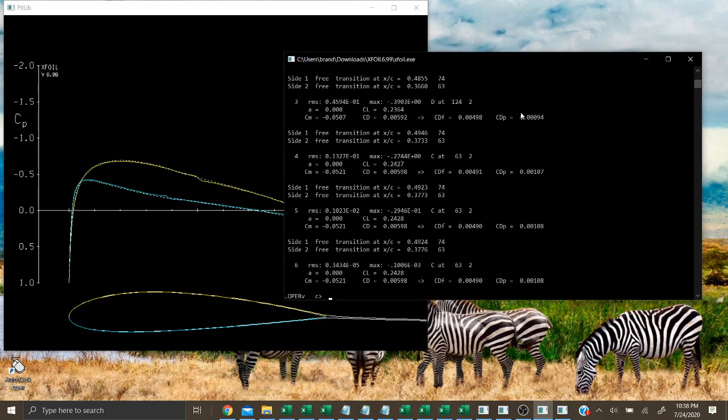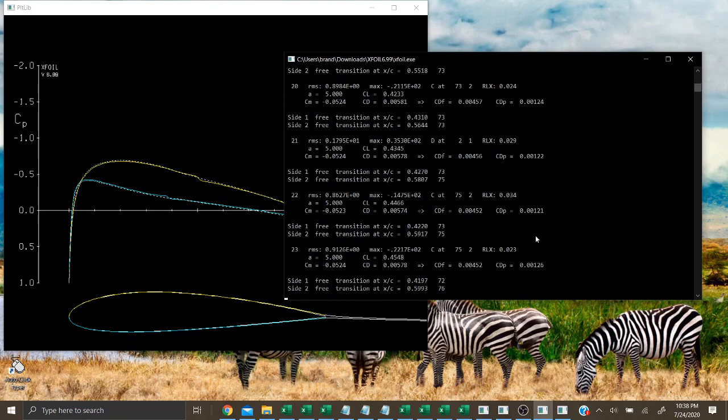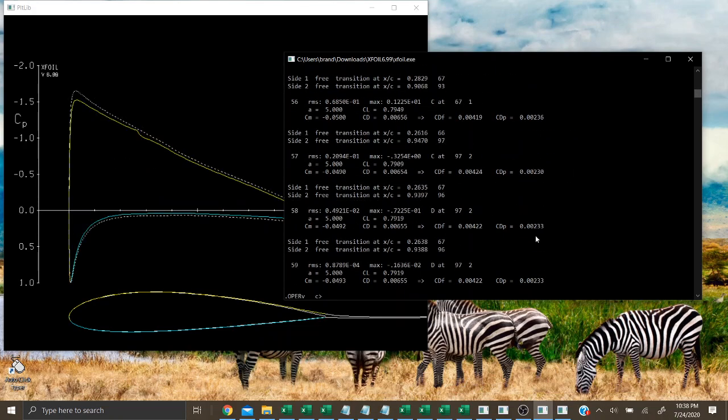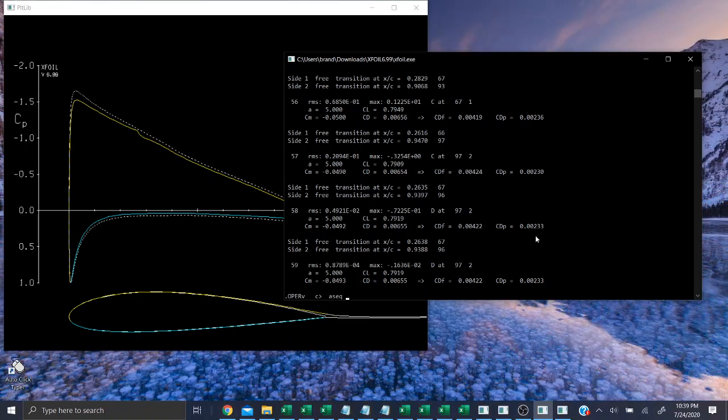We can reformat this data in other ways if we want, or test it with different angles of attack. So if I want to type in alpha 5, it will calculate it to that. In this project, we did have to do between an alpha of -5 to 15. So the way we would do that is ASEQ, or alpha sequential. And you could just type that in, or you could type out you want it from -5 degrees to 15 degrees with 1 degree iterations.